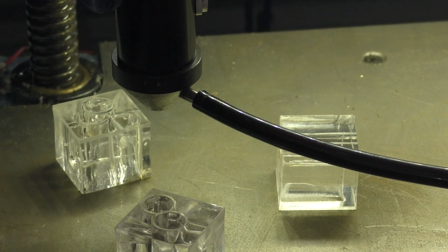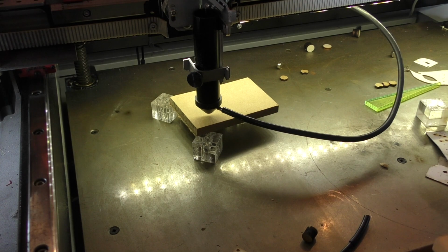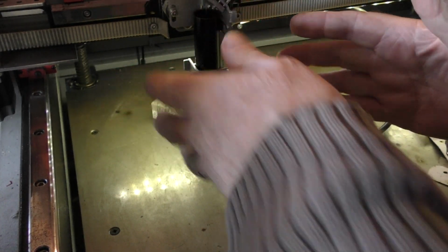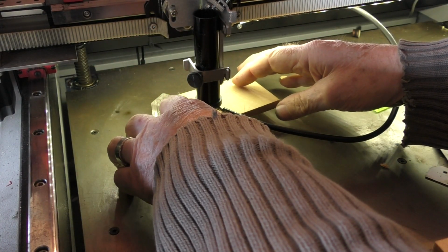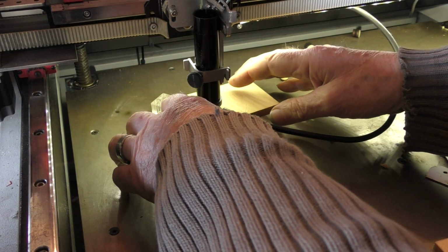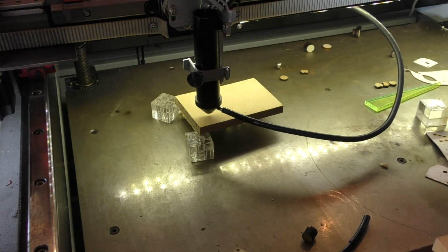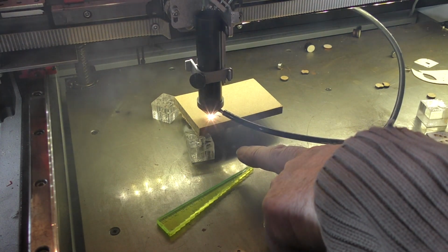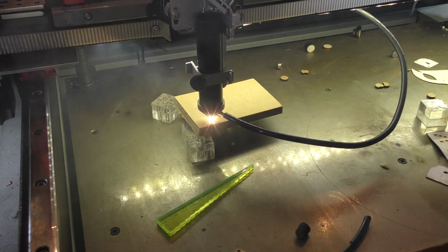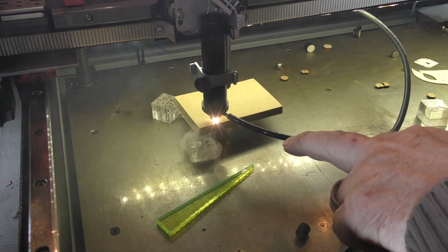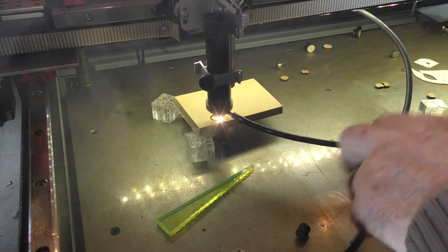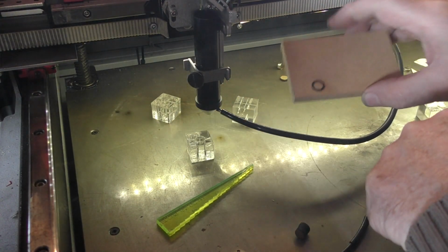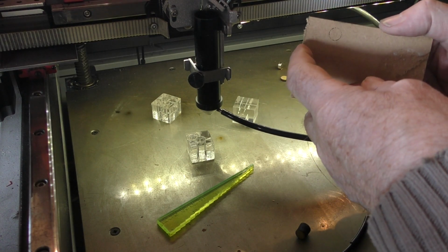No hint of it coming through. Now, as I move away from the corner of the machine, the cut is getting sharper, the beam is getting smaller. I've just moved a little bit away from the back of the machine where the cut was rubbish. Let's give it a try here. And we've definitely got a burn taking place because we've got smoke coming out underneath. We can see the reflection of the flames underneath there. Now, I would say that that's quite a thick burn.